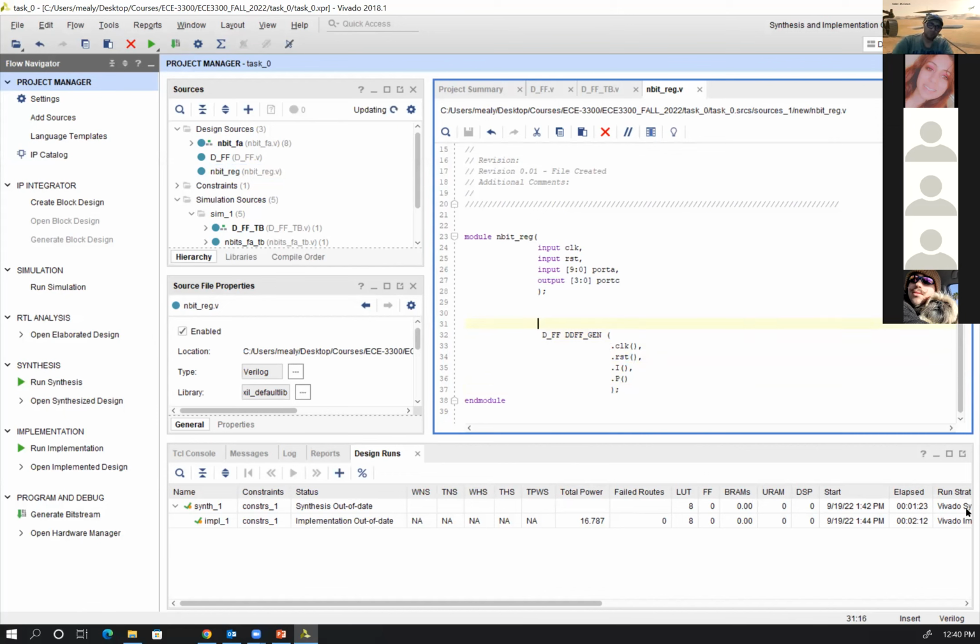Right now, is this register synchronized or asynchronous? What does synchronized mean? That means every single storage element inside the register uses the same clock. Imagine I have many flip-flops all connected in and out. That's called parallel in, parallel out, right? That's a register. That's one of the configurations we learned in 2300. So in that case, I can just use the clock as it is.